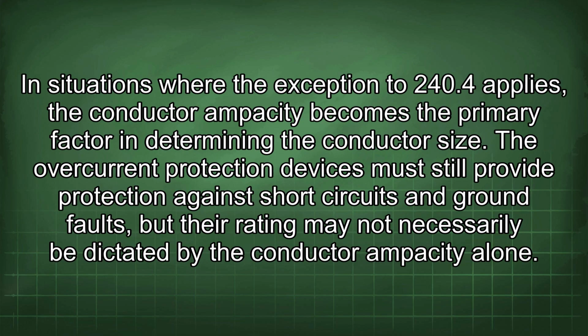In situations where the exception to 240.4 applies, the conductor ampacity becomes the primary factor in determining the conductor size. The overcurrent protection devices must still provide protection against short circuits and ground faults, but their rating may not necessarily be dictated by the conductor ampacity alone.